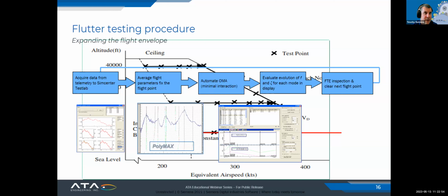So let me think about it. During the ground testing, we studied the configurations of one pilot in the front and two pilots, and tried to give a nominal case: what if the pilot had a really big meal the night before, and tried to bound that problem. There was some effect, because the glider is overall relatively lightweight, but it wasn't significant enough to dramatically shift the dynamic properties of the aircraft.